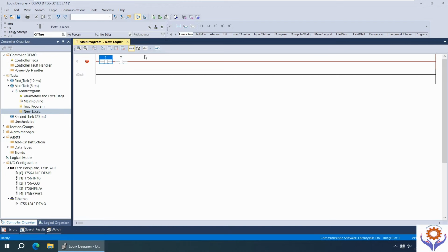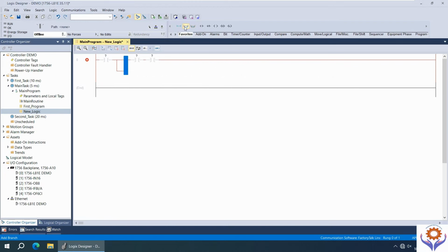So it is very easy to understand how to add this ladder logic. And also, see here, I can drag and drop the ladder logic. Normally, like the simple operators, this means operands. This normally open, normally closed, or any coil or contact, you can just drag and drop in the rung. It will directly insert. If you need to add one more, see here, branch or sub branch, you can add directly. Just click your cursor and add directly.